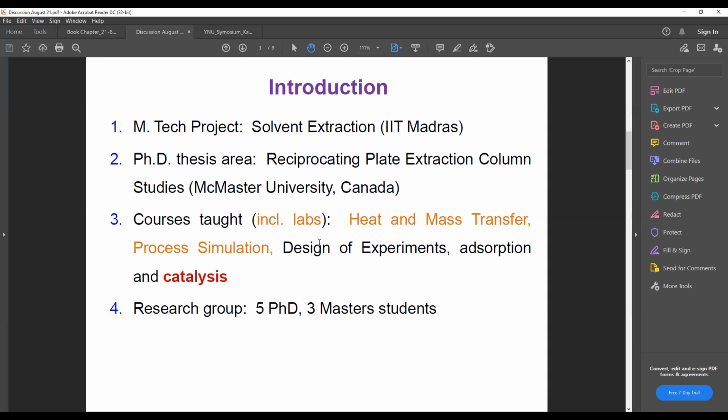I gradually became better at experimental work, and what fascinated me during my experimental program was that the direction of mass transfer plays a very important role in the bubble size or drop size distribution. If the mass transfer was taking place from water to oil, the drops were much smaller, and when the mass transfer was taking place from drops to water, the drops became very large. We found reasons for it in the interfacial tension gradients, and it was really exciting work.